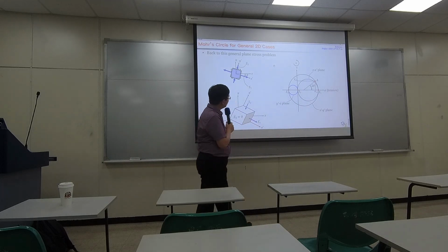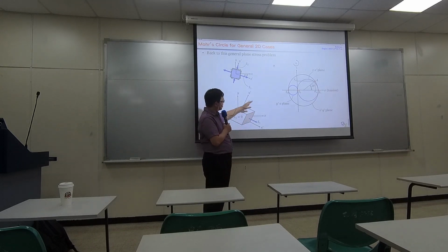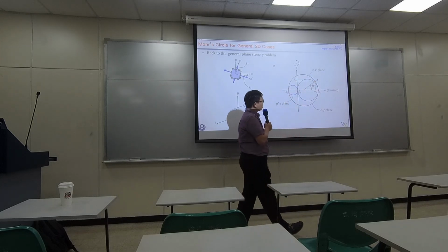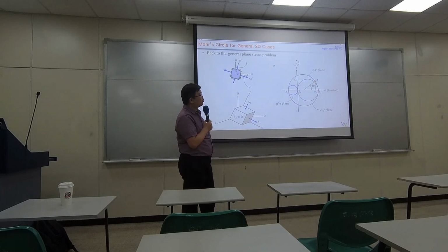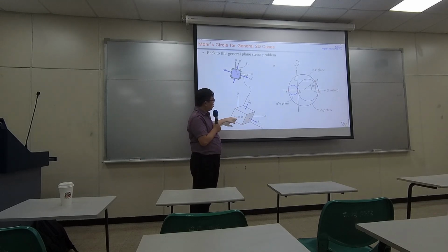Usually the Mohr circle that we work on is the one between first and second, the largest one, which is the Mohr circle we usually draw. We don't even draw the Mohr circles along the other 2 planes. However, keep in mind that there actually exists stress analysis along different directions. It's only because they are smaller.